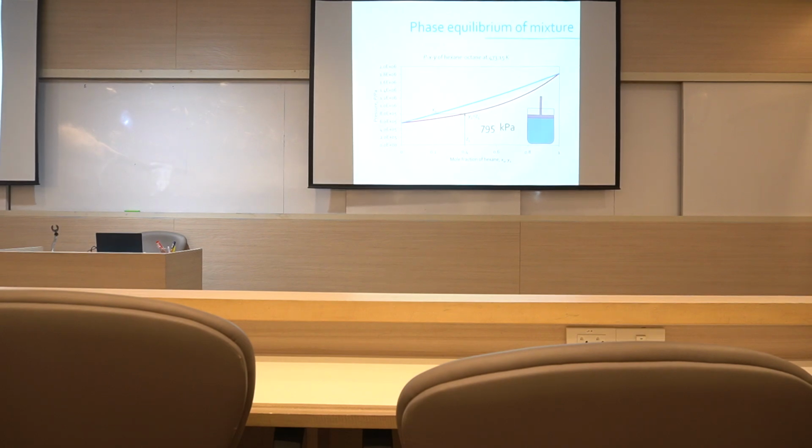Even though it says dew, which refers to liquid droplets, it actually means the last point where vapor could exist alone. If you go past this dew point into the middle region, you will start to see some liquid. That is why this curve is called the dew point curve. If you cross this boundary, you start to see some liquid droplets.